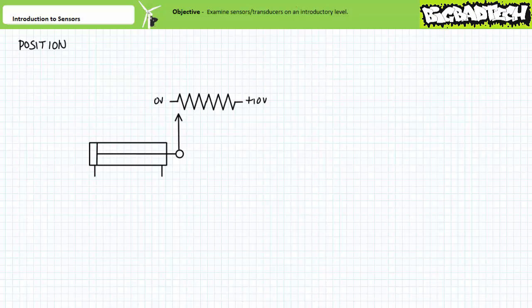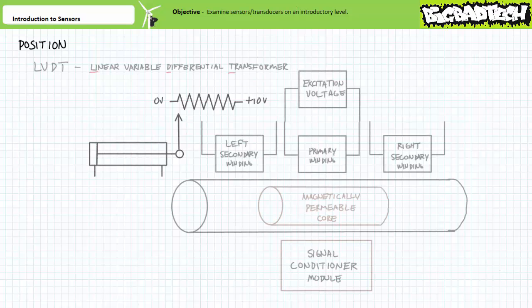At commissioning, the zero and span of this potentiometer-based position sensor would need to be adjusted for full retraction and full extension. Assuming linearity, and let's say a cylinder with a 10-inch travel length, just to keep the math easy, the 10-volt output range is broken into 1 volt per inch chunks. The problem with this contrivance is that it's riddled with inefficiency and mechanical problems. The wire could stretch over time, the reel could bind, or any number of tolerance issues could develop, all serving to decrease the accuracy and response of this system.